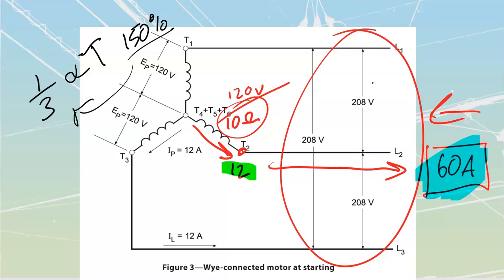Because it is going to be 1/3 that we're going to start on, this is a hard and fast value. It doesn't matter how you do your math or what the motor is going to be, you will always end up at 1/3 of your startup torque for these. We are going to be limited to light motor loads or motor loads that can be started unloaded. They give you examples of fans.